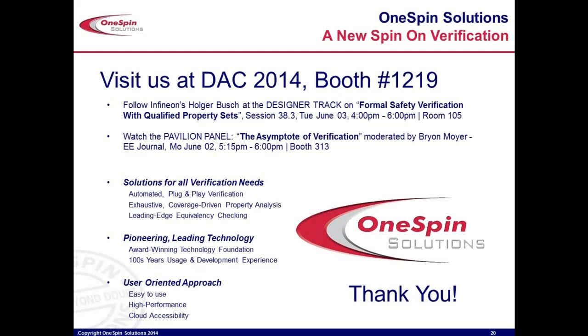Well, yes, this is possible today if you express a functional coverage point in SVA or PSL. Obviously, the problem is that a lot of people have coverage expressed in, for instance, UVM or in Specman, with classes, and we are not able to read this kind of language yet and see if the assertion is covering this.